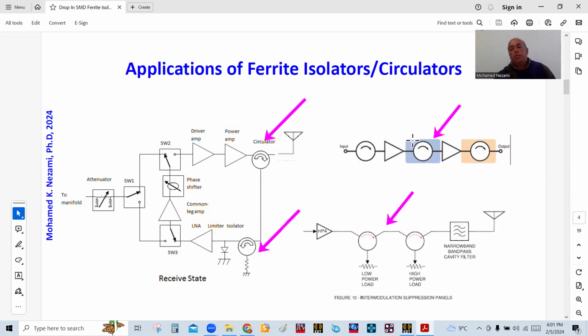Then in this case, for instance, in here, this is for power amplifiers. Anytime you have power amplifier stages where you want protection and to maintain good return loss, in one particular case it is because you wouldn't want any of these devices to oscillate. If you didn't design them carefully and there's a likelihood that these devices will oscillate, the best thing to do is just throw isolators in there. Isolators will make it always see a constant, resistive impedance.